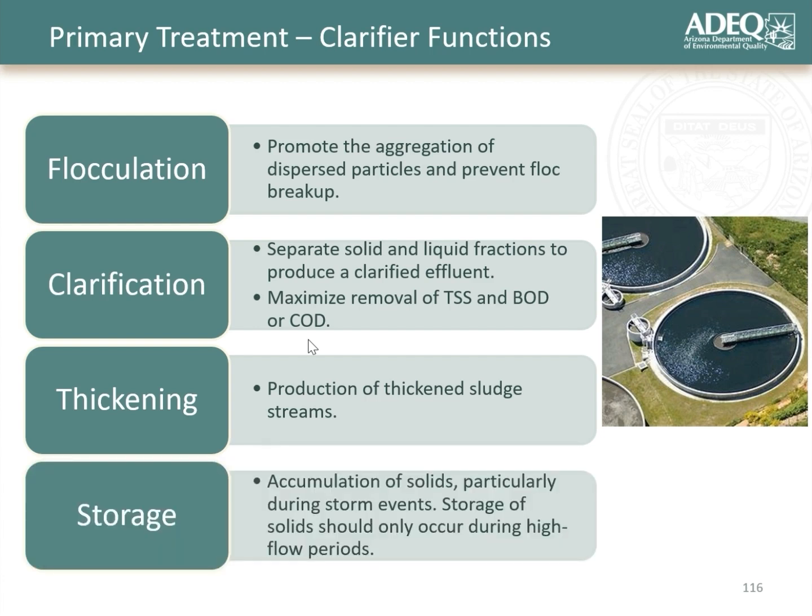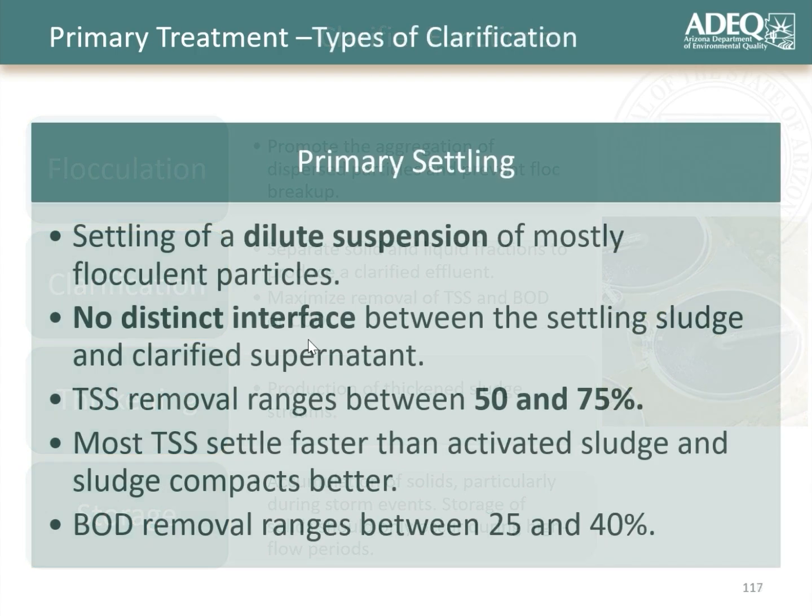Lastly, you can use your clarifiers as short-term storage of solids in case you have some issue with your downstream solids handling process. But this is only a short-term use, because a high flow event could happen, and then all of a sudden you have solids washing out of your system further downstream and potentially overloading your other treatment processes. So when we think about primary clarification, once again, we're settling these larger particles that want to settle out.